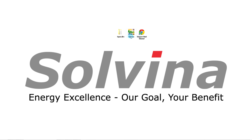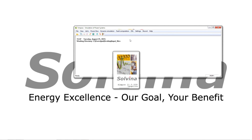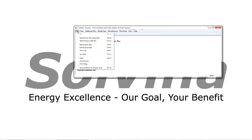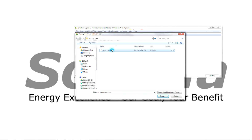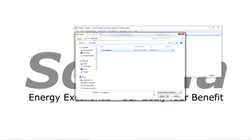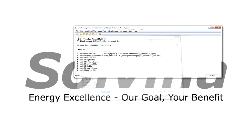First, we start by starting Simpow. If directory is not set already, we select the current working directory from Settings. For Dynpow to work, it needs the stationary solution result file from the Optpow run and a Dynpow input file. First, we select the power flow result file obtained from our previous Optpow run. In this case, it is autres_curse.curse. Next, we select the Dynpow input file, which is already prepared and given in the input files.